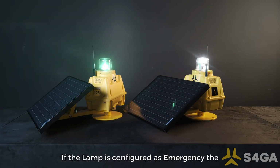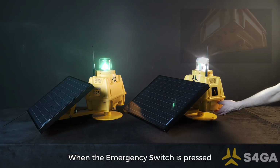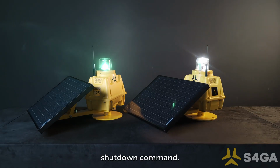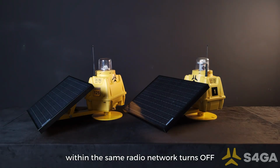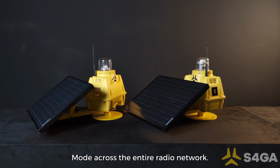If the lamp is configured as emergency, the shutdown procedure is as follows. When the emergency switch is pressed quickly 4 times, the lamp sends a radio shutdown command. This command is received by all lamps operating within the same radio network. As a result, all lighting units operating within the same radio network turn off simultaneously. Turning off emergency mode from a non-emergency lamp also disables emergency mode across the entire radio network. This ensures a reliable and synchronized power-off function across the entire lighting network.